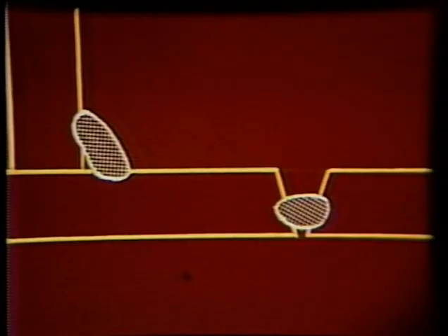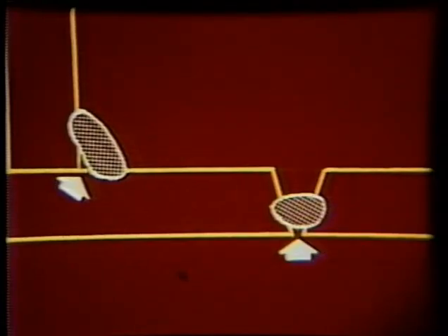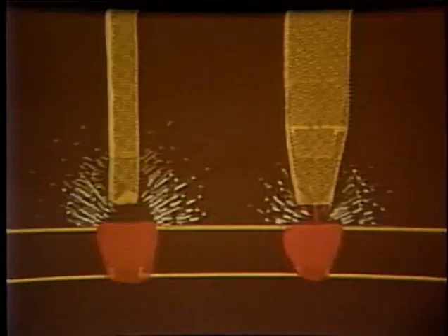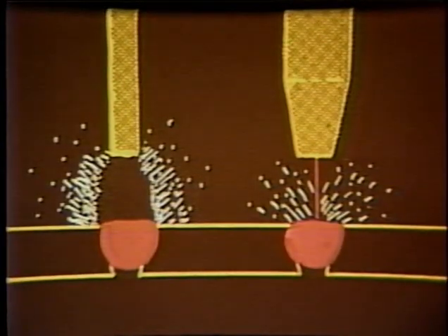The final defect to be discussed is inadequate joint penetration, or penetration which is less than specified. This defect is commonly located at the root of a weld and is generally caused by an insufficient heat input while welding. Too low an amperage is the usual cause. Holding too long an arc length or too long a stick out reduces the heat input and leads to inadequate penetration. Too fast a travel speed along the joint has a similar effect.